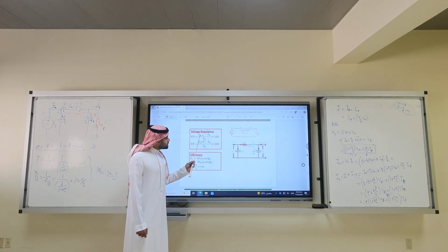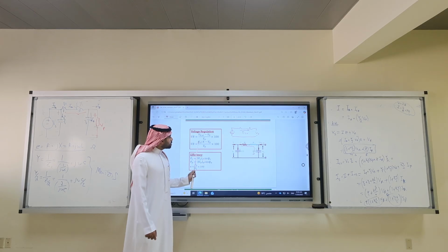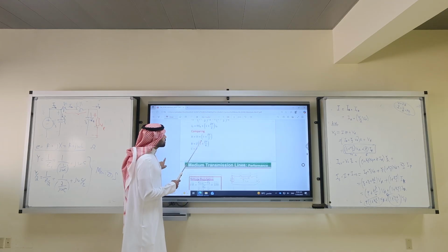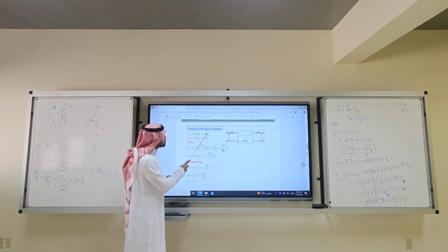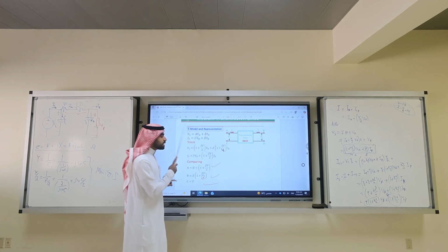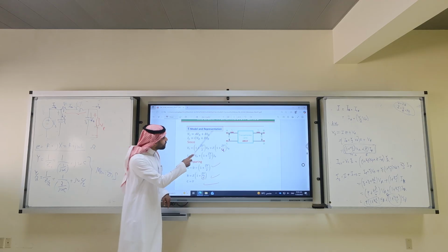So, to fix this equation, you have to get this output is Vs over A. Why is it Vs over A? Because go here, if you make IR 0, Vs at no load, or VR at no load, is Vs over A if IR is 0.